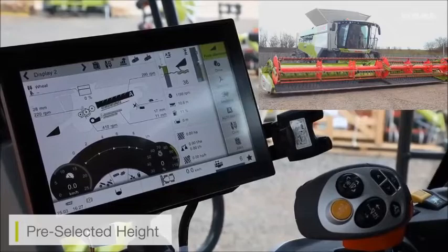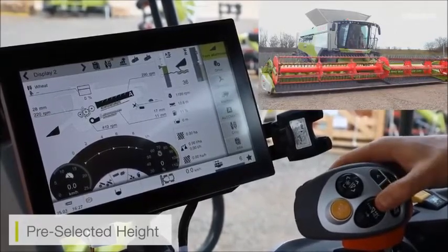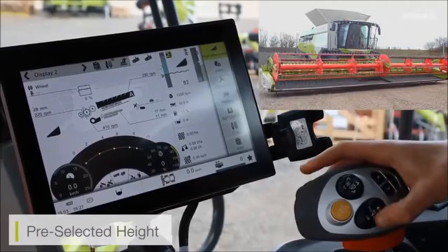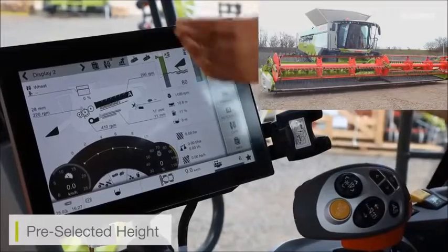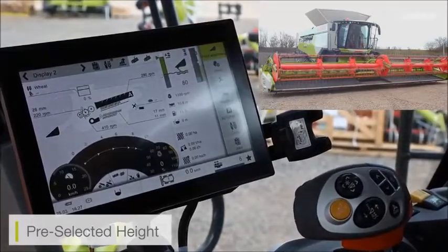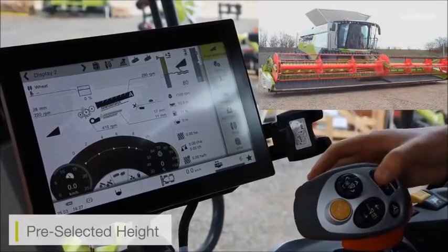Again, just the same as my pre-selected height, if I do need to pre-save a setting, all I need to do is move the cutter bar, press and hold the Save Auto Contour button, and now I can see I've saved a different position. Again, I can manually do this through the joystick, or I can do this through the Favorites menu.